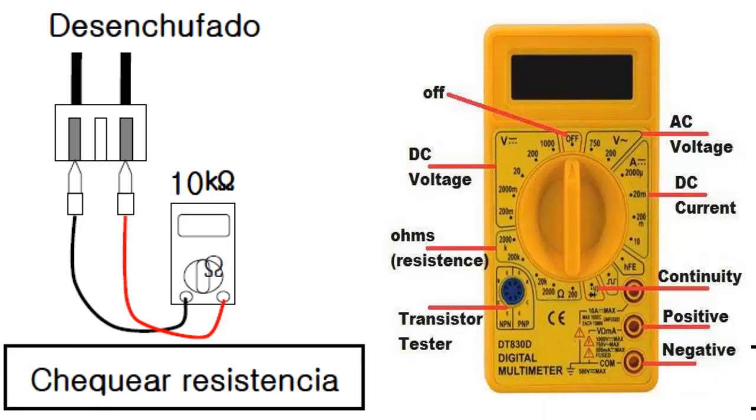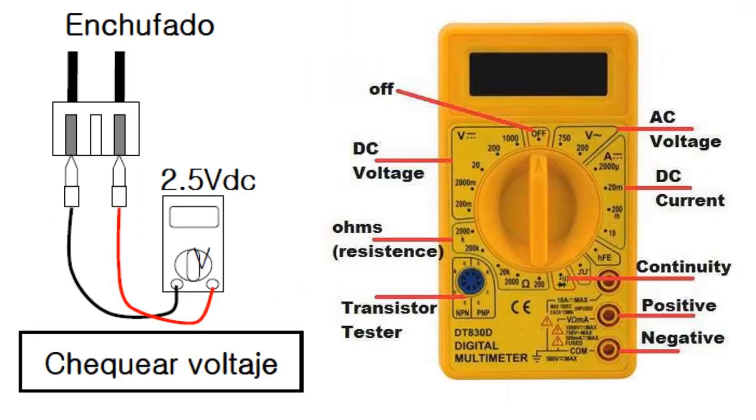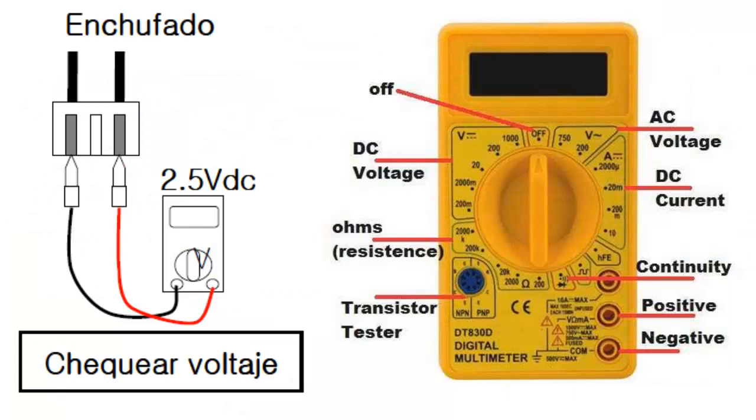It is also important to verify the power supply of the card to the sensor, in case the problem is in the power supply of the card. The card must supply a voltage so that the sensor can work. Then we must connect the sensor, and with the sensor connected, verify the voltage.